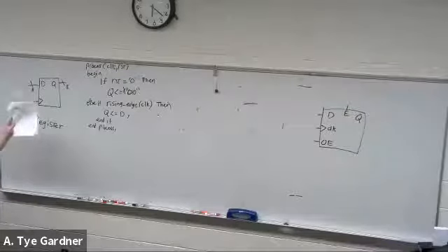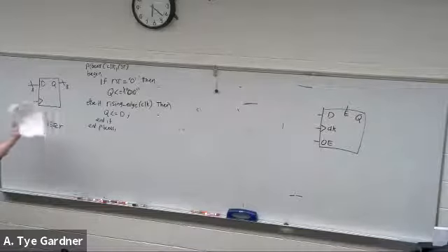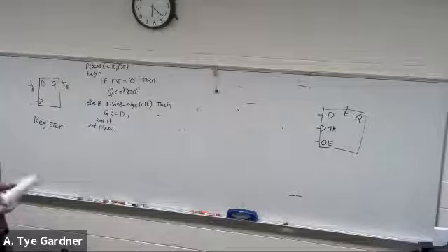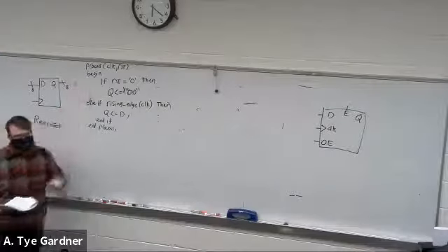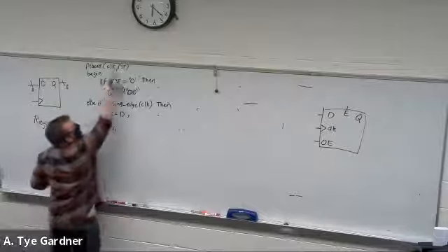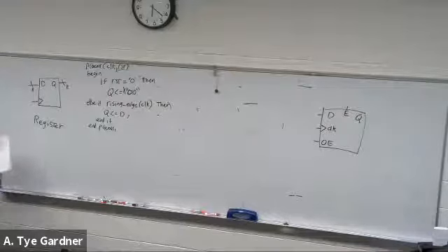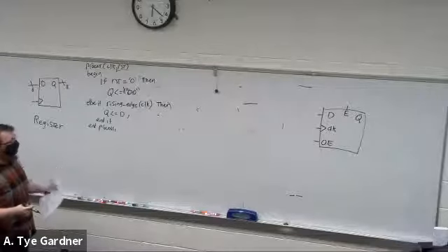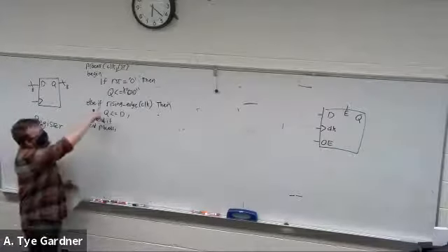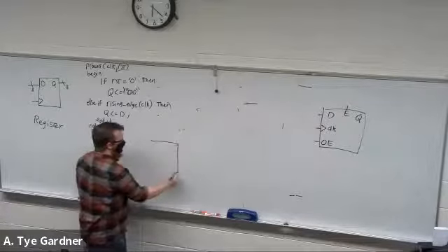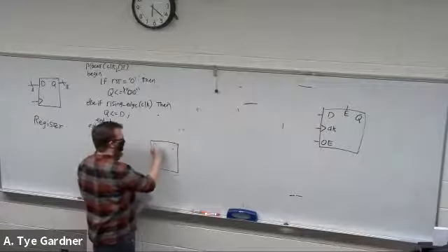So that's asynchronous reset. The other way that I kind of sketched out is a synchronous reset. Generally in this class, I will ask you to do this one. Don't forget the reset here because that will cause you grief. Don't put anything else in the sensitivity list because that will cause you grief. If you ended up with like your input D on the sensitivity list, I have seen this before in labs and it's not great.